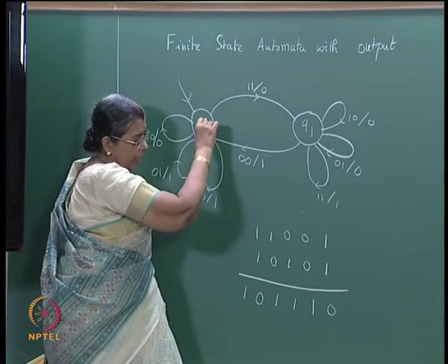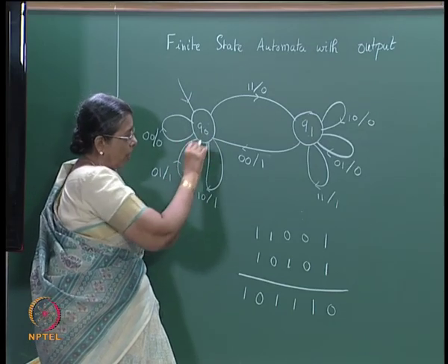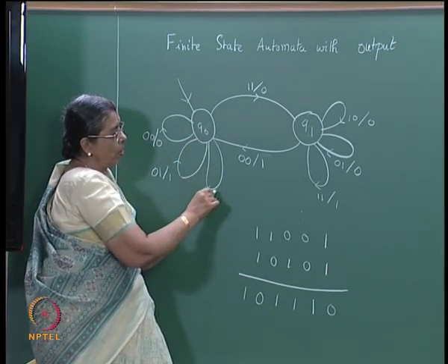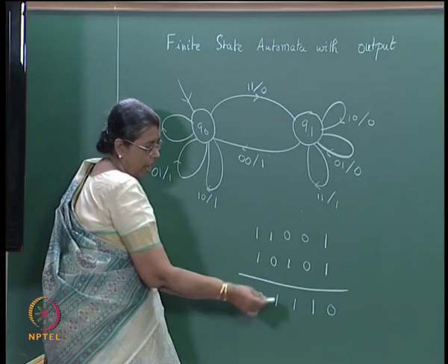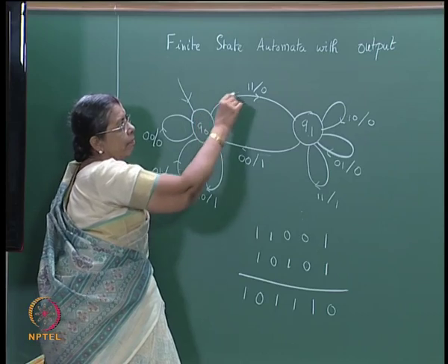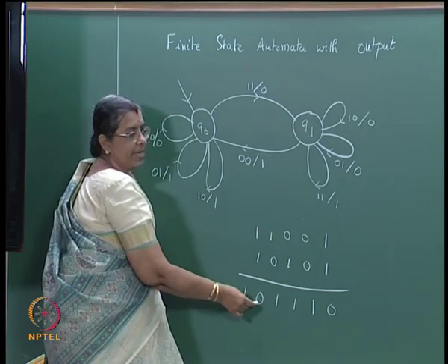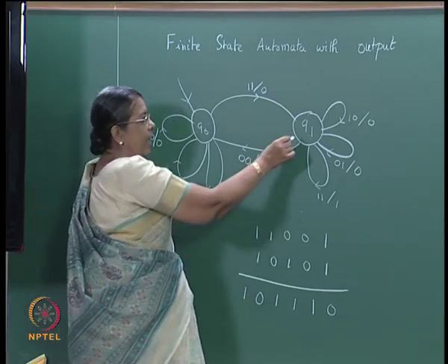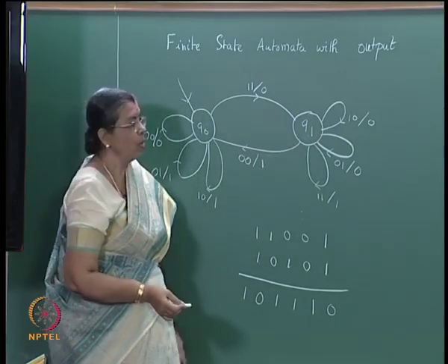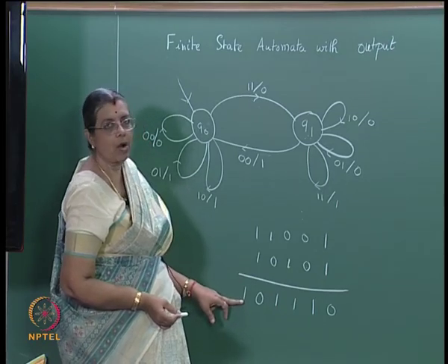In this state, a no carry state, when you get a 0 1, you output a 1, there is no carry, and you get a 1 0, you output a 1 and there is no carry. Now, in the no carry state, when you again get a 1 1, you output a 0 and go to the carry state, and in this state you are not getting any input, that is you have to consider it as 0 0. So, next instance, the last instance, a 1 will be output.